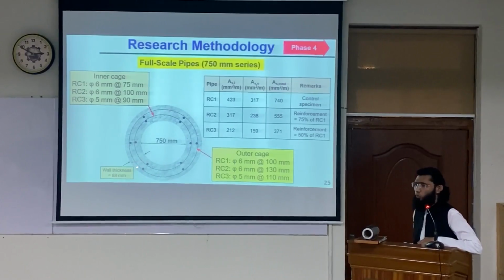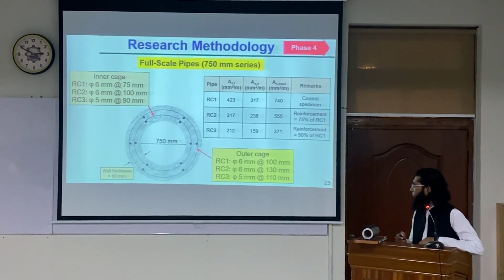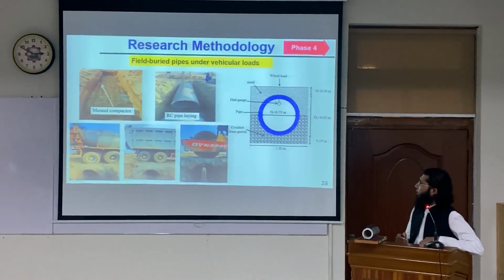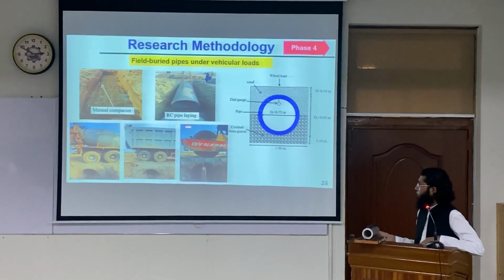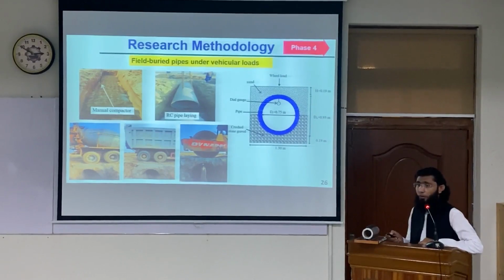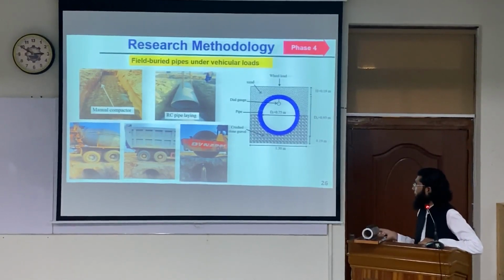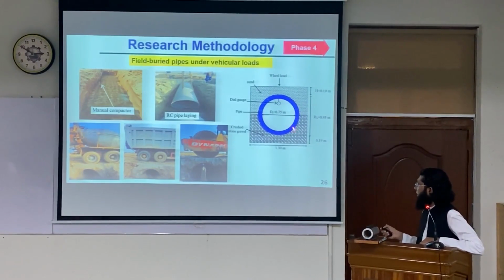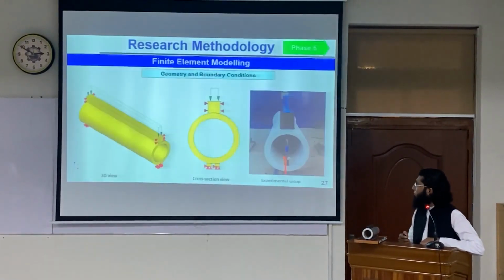Now the wall thickness was large enough for these pipes, so double reinforcement was provided in these pipes. And not only the lab investigation, but also field investigations were conducted. The pipes were installed in the field, and various types of vehicles available at the site, such as a transit mixer, dump truck, roller, and other vehicles, were passed over the field-buried pipe, and the deflection was recorded. This is a schematic of the whole setup.